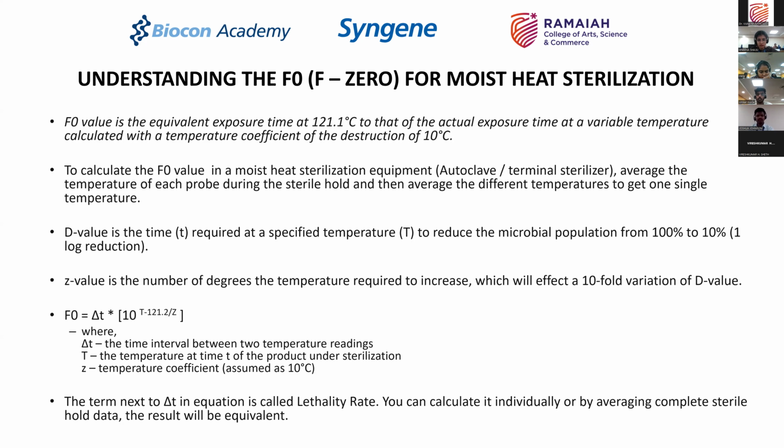When you are actually carrying out an autoclave cycle, you are not going to be able to determine the log reduction online, correct? Because to determine the log reduction on the spore count, you have to take the swab and plate it. You're not going to be able to do that in real time. You will just do the initial load and the final load, and you will see whether your reduction happened or not.